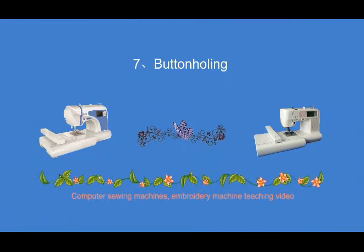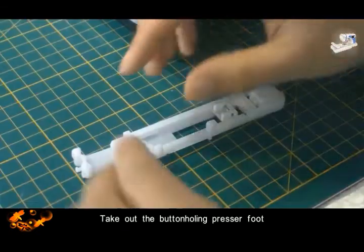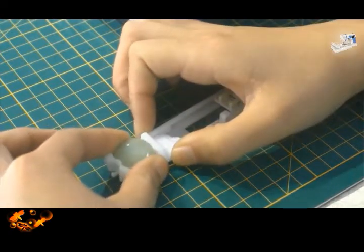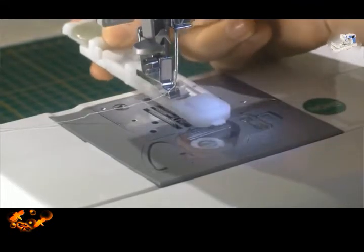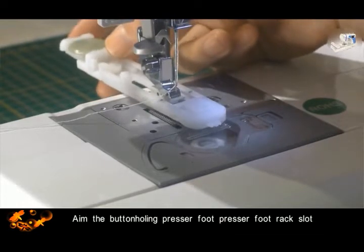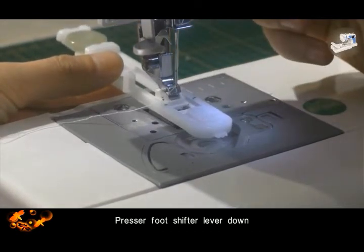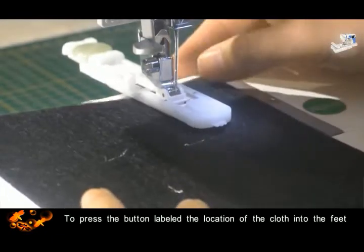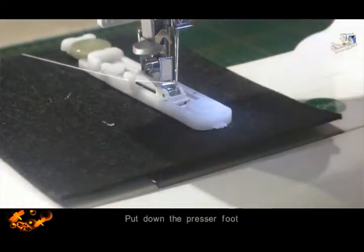Seven. Buttonholing. Remove the original presser foot. Take out the buttonholing presser foot, and select the button length. Aim at the buttonholing presser foot rack slot. Move the presser foot shifter lever down. Put the cloth into the foot at the location labeled for the button. Put down the presser foot.